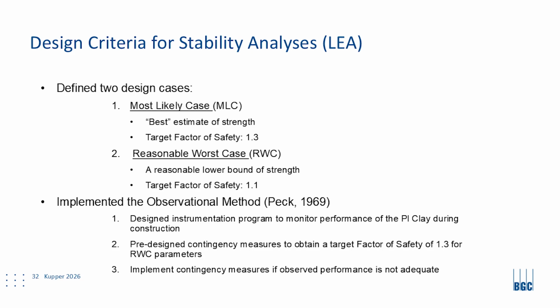You do your design for both cases. You try to match those design criteria for both cases. And then you implement the observational method. So you design your instrumentation program to monitor performance. You have your pre-designed contingencies.